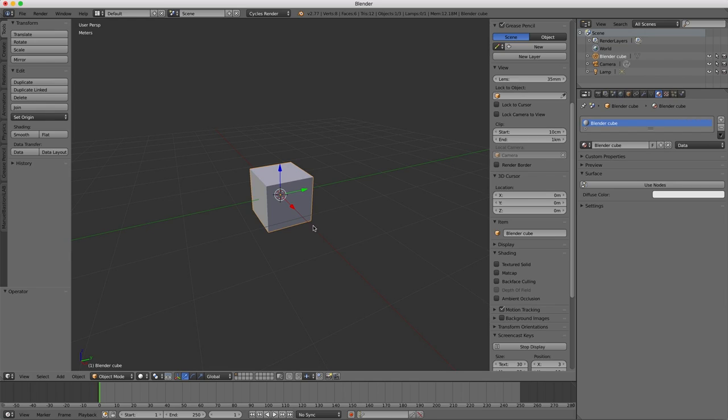There are a couple different ways to do this, but the way I like to transfer projects into Unity is by using the FBX file format. Now you can drag a blend file directly into Unity, but all it does is open up Blender in the background, use Blender's FBX converter to convert the file to FBX, and then close Blender in the background. So if it's going to use Blender's FBX converter anyway, why not go ahead and do it here?